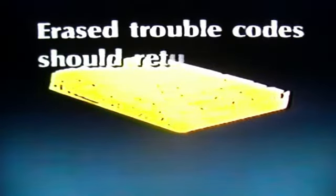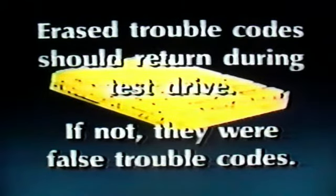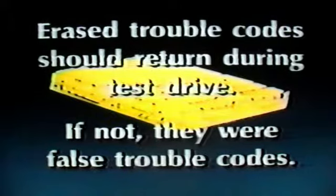The obvious question is, what happened to the other codes that were previously stored in the computer? The answer is that the trouble codes you erased in the memory are supposed to return during the test drive. But if they don't return, then this tells you that they were false trouble codes and there's no real malfunction. False trouble codes can be the result of many things. Most often they occur because of a repair or service function performed at an earlier time.